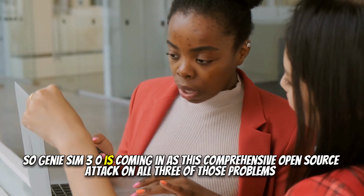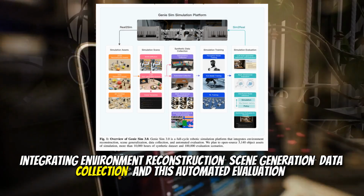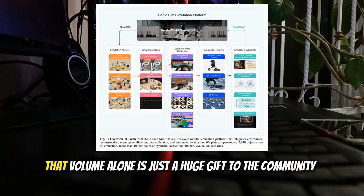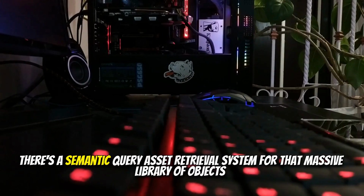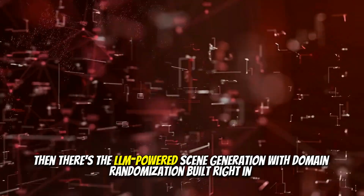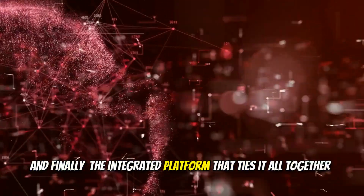So Genie Sim 3.0 is coming in as this comprehensive open source attack on all three of those problems, integrating environment reconstruction, scene generation, data collection, and this automated evaluation. And they're open sourcing 5,140 assets and over 100,000 evaluation scenarios. I mean, that volume alone is just a huge gift to the community. It really is. And to make it all work, the platform provides 5 critical new modules. There's a semantic query asset retrieval system for that massive library of objects. Then there's the LLM-powered scene generation with domain randomization built right in. The 10,000-hour dataset itself, the evaluation benchmark. And finally, the integrated platform that ties it all together.